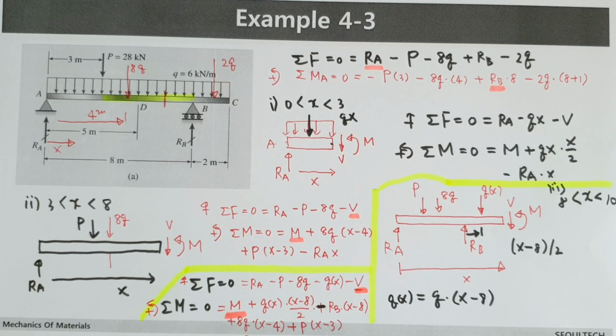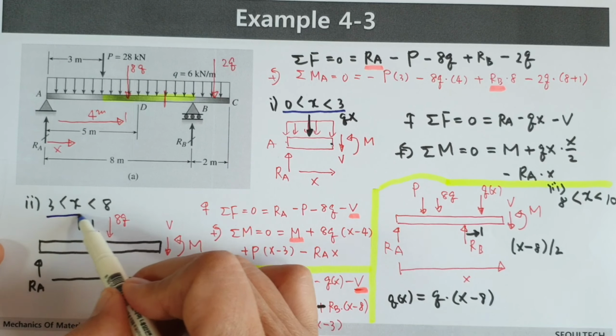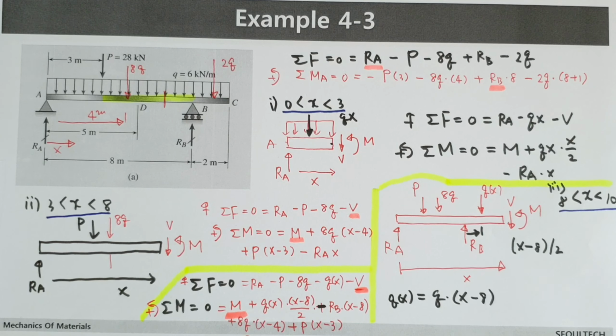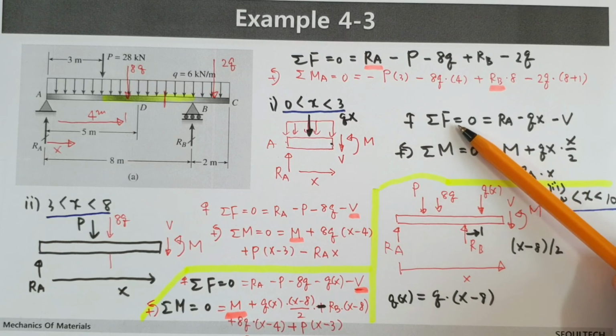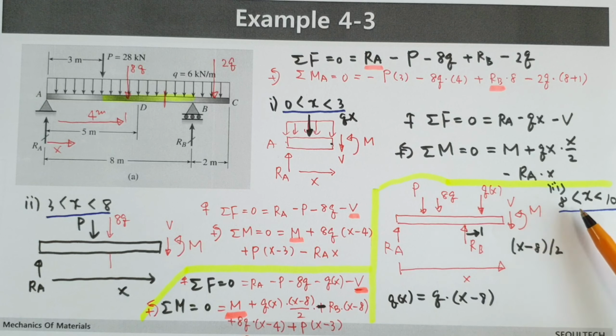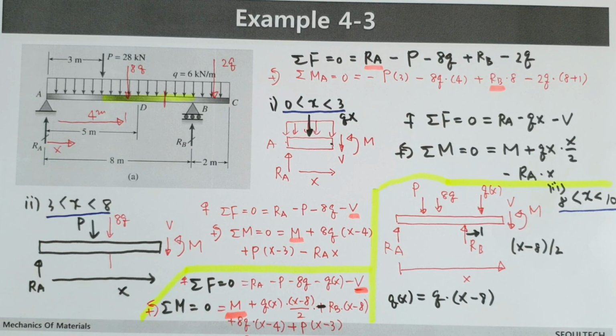Next stage, we want to calculate shear force and bending moment for each case, this range, the second range, and the final range. The basic approach is that we can use shear force and moment equilibrium in each case. And the important thing is how we deal with distributed load.